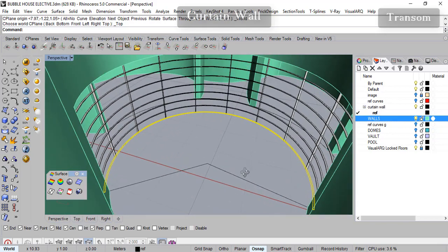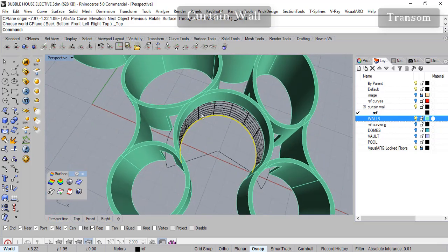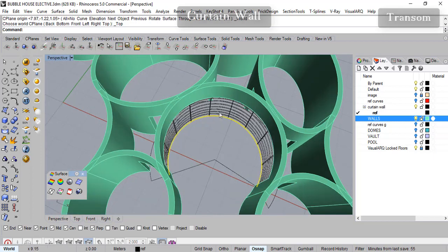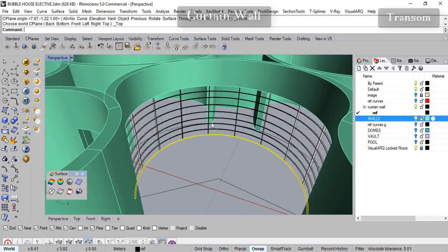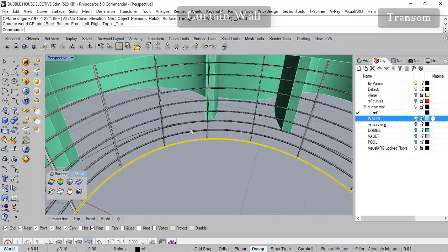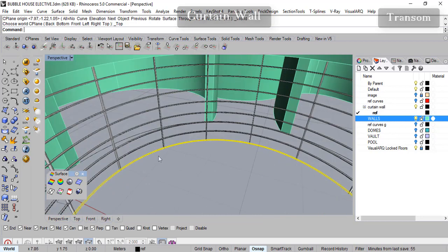My guesswork is that since this is a hall and there's a passage along this, we might want to just open one or two of these and leave the rest as is, fixed and stationary, because we don't want any access from here. So let's assume we need to cut away these two openings into doors, so we need to cut away the sash bars.